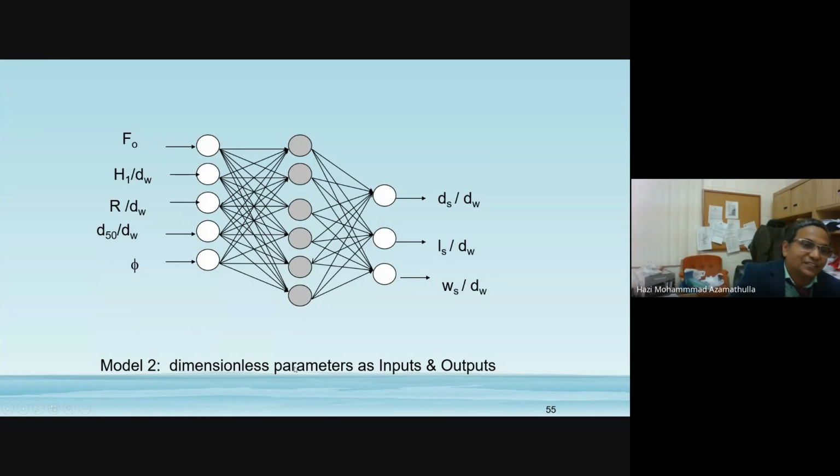You can see here the Froude number, this one grouped, meaning non-dimensional depth of scour relative to the tailwater level, relative location of scour, and width of scour. So here are relative head, bucket radius, then fine, and lip angle. The lip angle is very, very important, right? Is that okay? Next please.